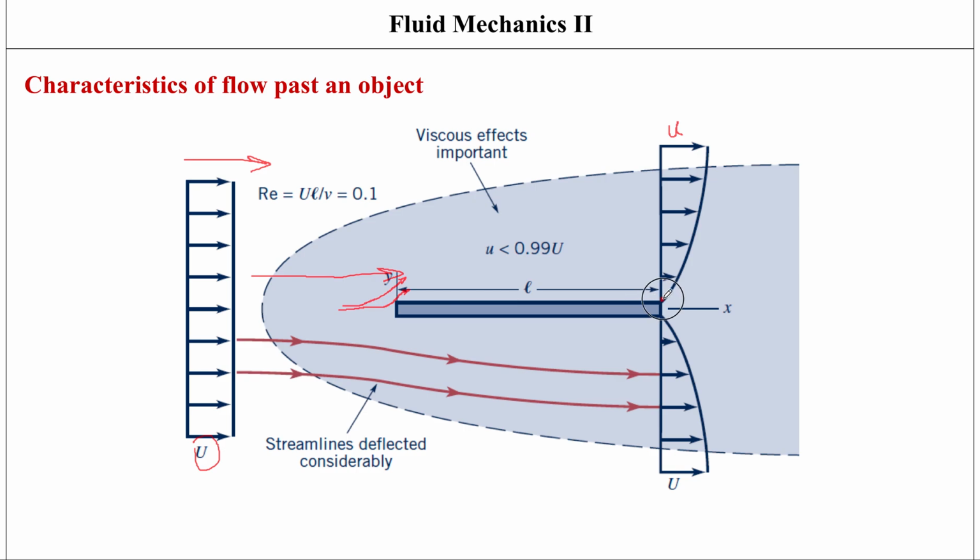So that is what is being indicated here. And then the velocity is going to be increasing once you go away from the plate or go away from the pipe wall. That is exactly what is happening here. And then the velocity is going to keep on increasing, in this case for the flat plate, until you reach the maximum velocity that is already the velocity of the flow. Okay, so this boundary layer, then you've got to find a point where you can basically say that this is as far away from the plate where the viscous effects hold any real significance.